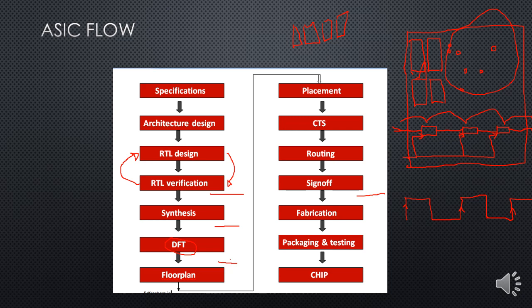In layman's words, the time taken for the signal to reach from the clock source to the memory elements, we call the insertion delay. We want to maintain that insertion delay constant in all of them.